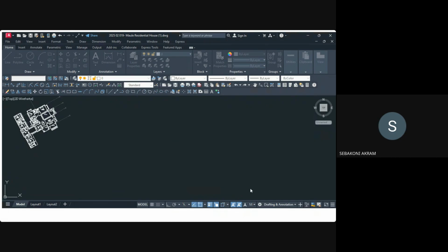Then I press OK. You see, it brings you are about to delete 6 layers, some of which are referenced in blocks. You getting me? All objects on those layers will be deleted, and referenced blocks will also be redefined. So do you wish to continue? Yes, because the layers that the objects that I want, they are already aligned to what? To my layers. The two layers. That's why I exploded and I bursted.